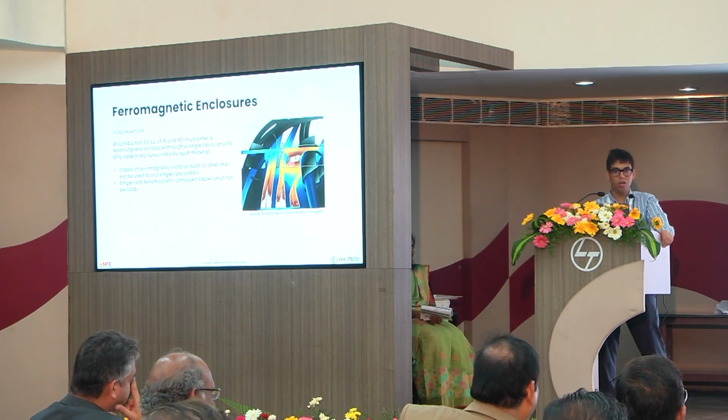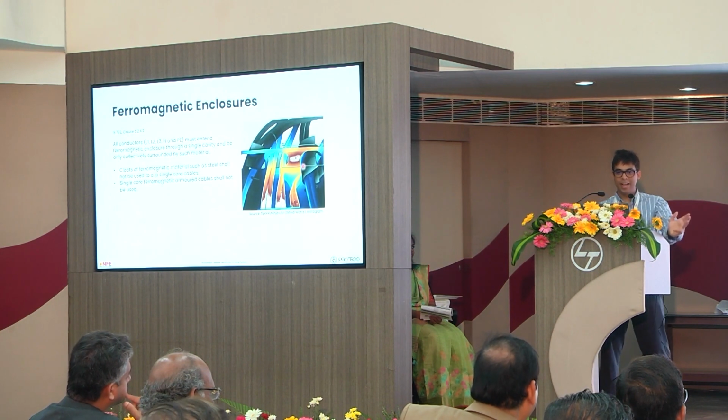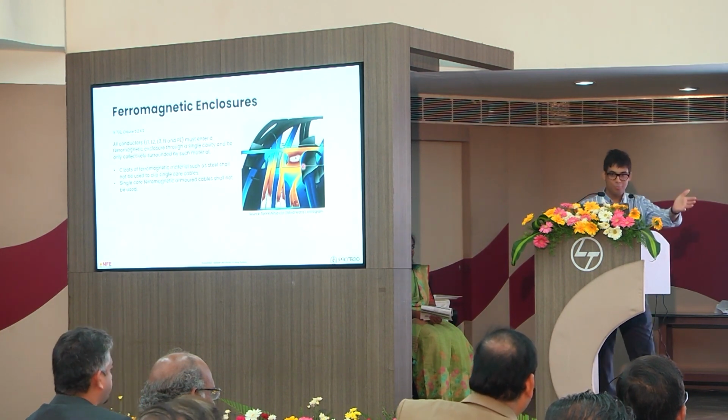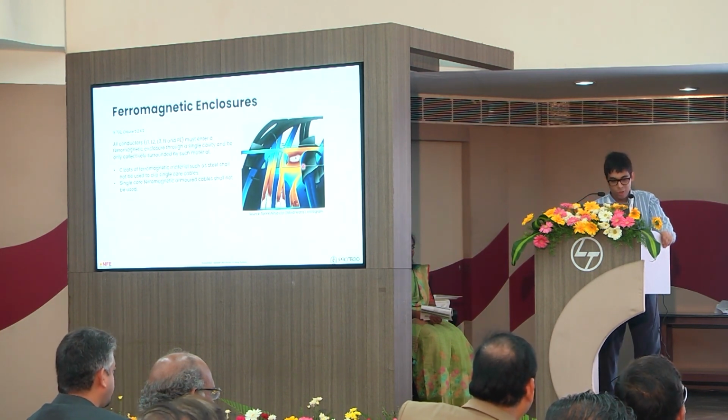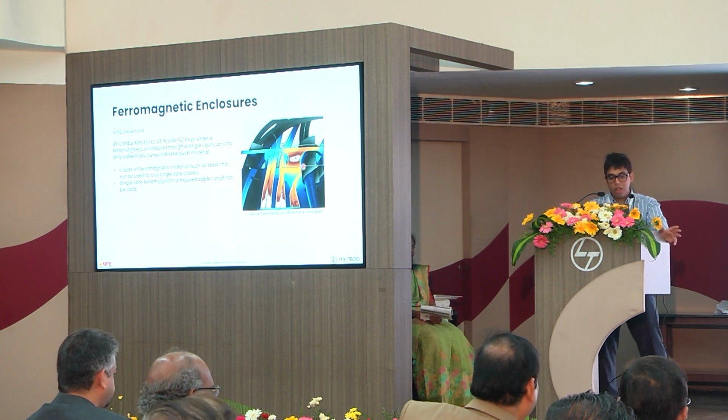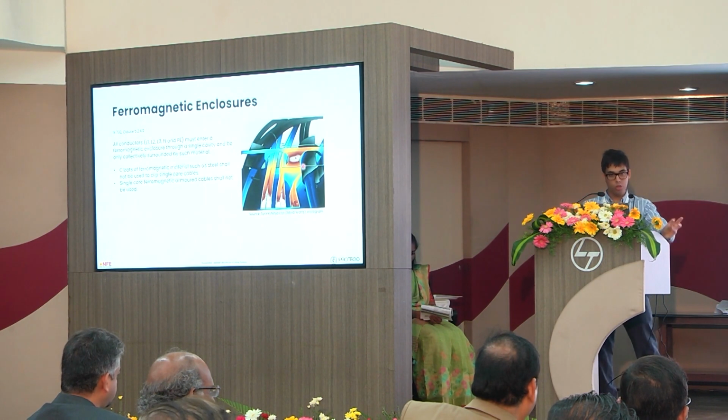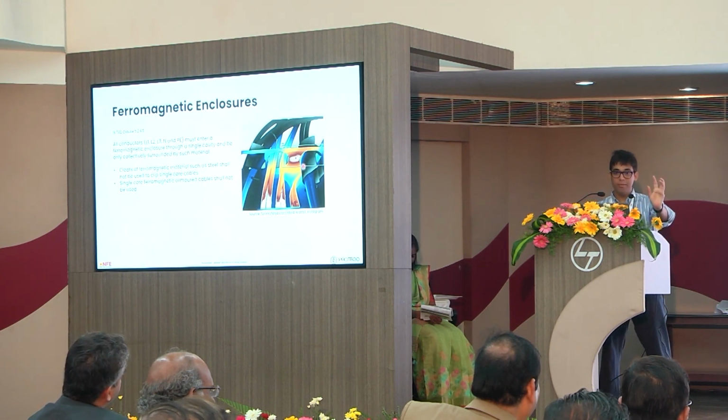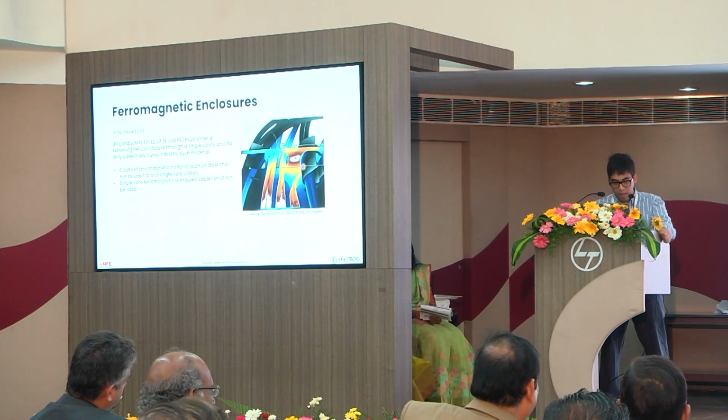Is it visible to all? It's heating up. That's the eddy currents. Basic stuff we learned in college, right? So if they enter, all the conductors, line 1, line 2, line 3, and neutral, and protective earth must enter through a single cavity. And they must only be collectively surrounded by such material. Otherwise, you're going to have eddy currents.